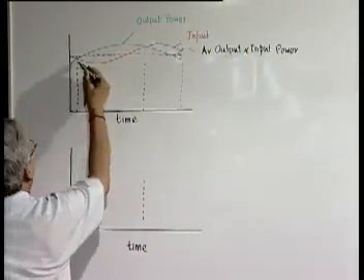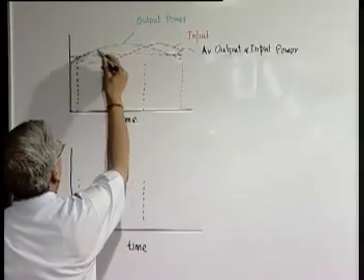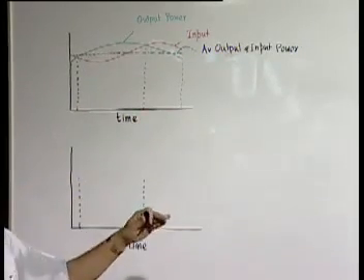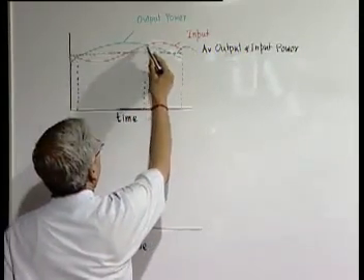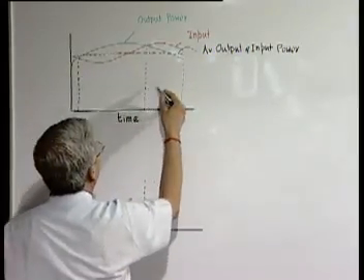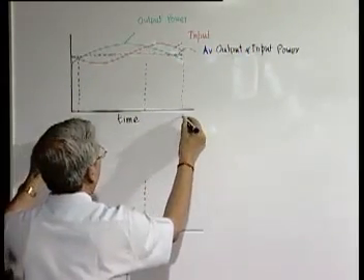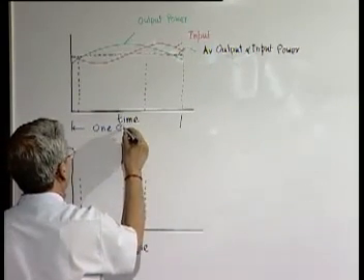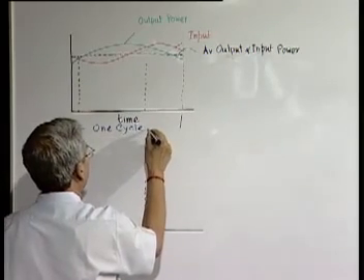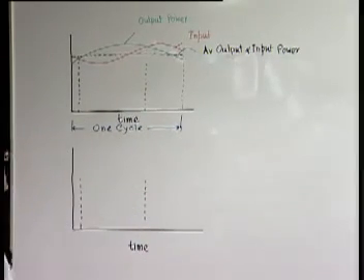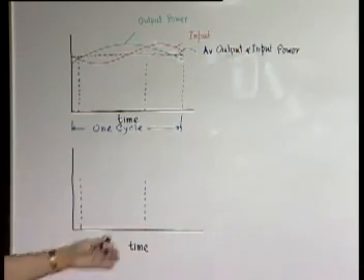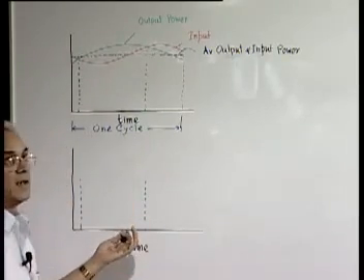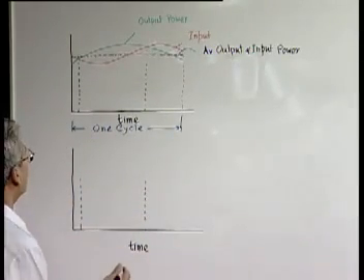What is going to happen during this period where output power is more than the input power is obvious, the engine speed will come down or slow down. Similarly, in this period, from here to here, this is one cycle, because in steady state everything will be in cyclic pattern. This is one cycle, after which the pattern repeats. So, here input power is more, so obviously the speed will increase or the system will accelerate.